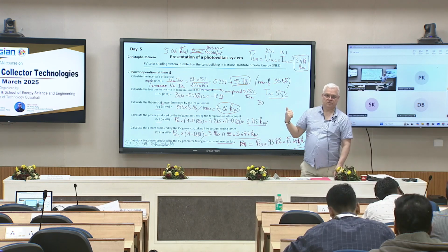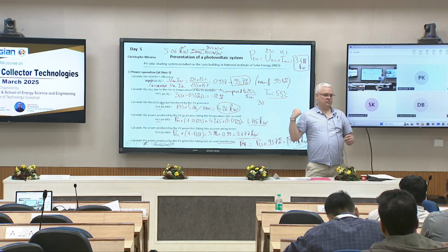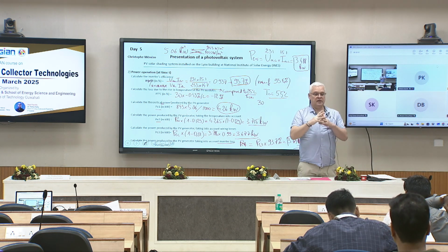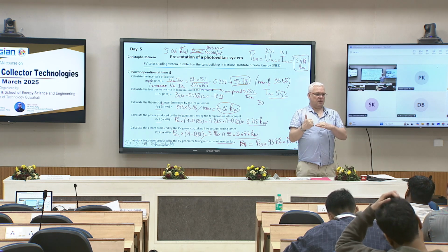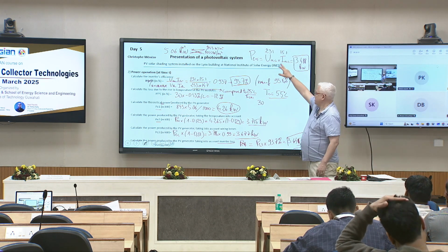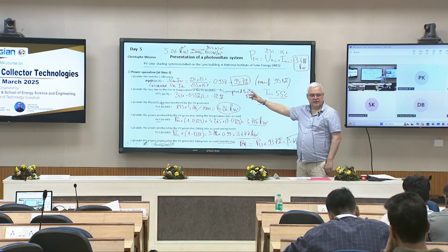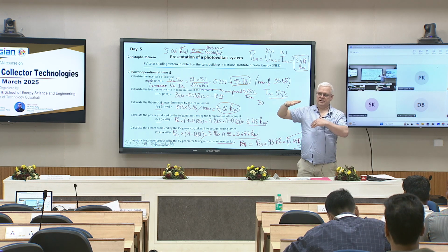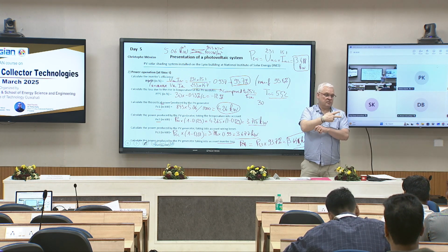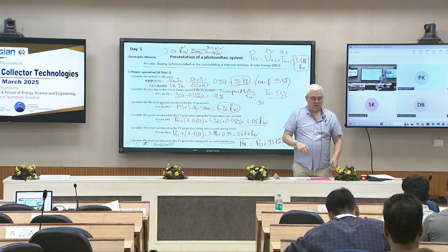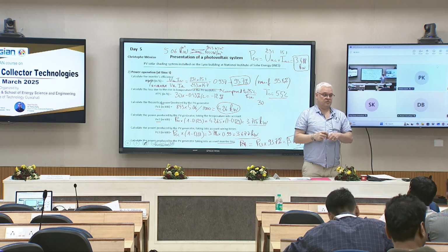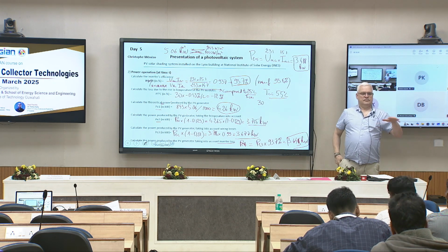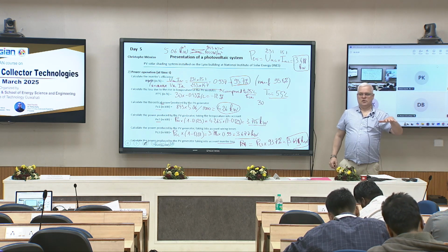So when I was presenting Heliocity, it is one of the things that is constantly checked. Okay? Power which is extracted from the data after the inverter and considering all the loss. And if there is a discrepancy, that means that maybe one cable is cut or one cable is overheating because there's too much Joule effect or things like this. Okay, it's a way to check if it's fully consistent.